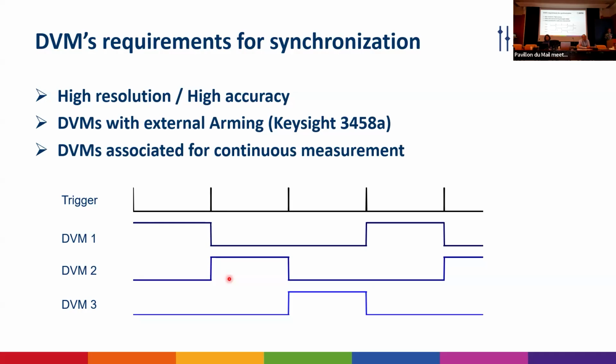So you have the option between these instruments or developing your own voltmeter, and in this case, you can manage the triggering more or less as you want. Jan Robinson will talk about homemade voltmeters. I will talk about the 3458. Typically on the 3458, if you send a trigger on it, the 3458 will require 100 or 200 nanoseconds to understand that you will have to measure something.